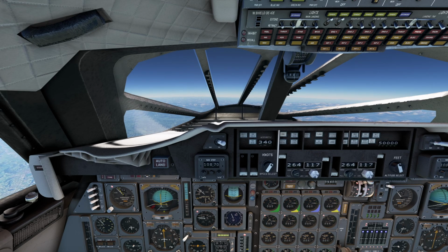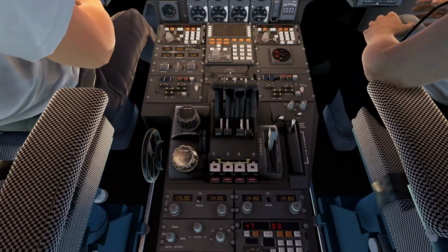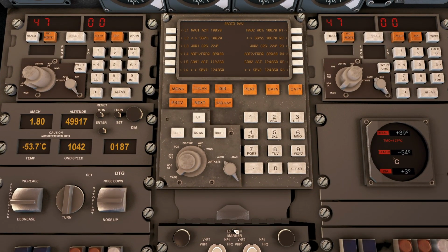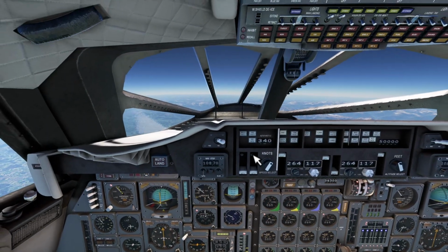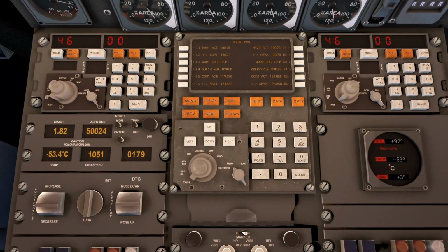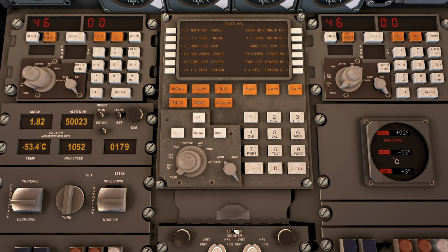We are approaching 50,000 feet. Our temperature has come down a little bit, which is good, but now we're losing speed, overshot a little bit, so immediately go to max climb so that it continues accelerating. It's a very delicate process. You're in this Goldilocks zone. If you're in there, the plane is behaving smoothly and no problems. If you have to correct, you have to work a lot. Descend, ascend, etc. I think we are just about in this Goldilocks zone.